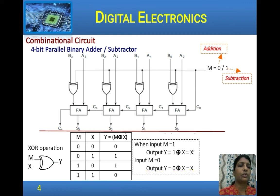So, to this XOR gate, when addition should be performed, 0 is given as one of the inputs to each of the XOR gates, and the other is the number that should be added, that is the addend. So, the output that we get is the addend as such. When M is 0, the output is X, so the output is B0 as such. So, addition is performed by this circuit.